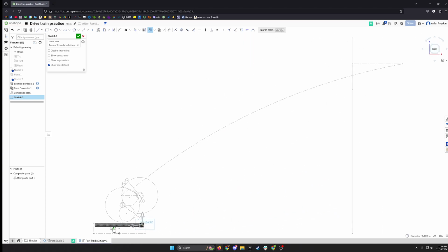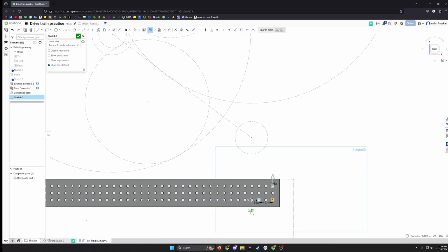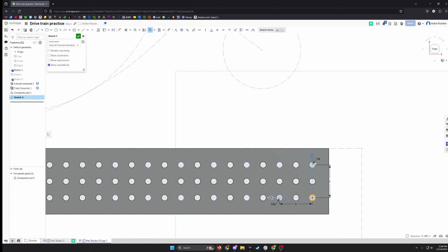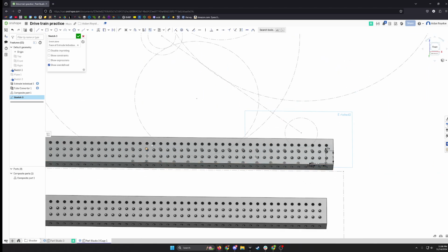And that's about where we want it, because this is the farthest back point of the indexing roller, and we want it to be a little bit farther behind that, so we have some extra support. So then we have all this bottom row done, and we can kill 2 birds with 1 stone by just coming up here to this 1x and just changing that to a 2. And this 1 inch is still correct because it'll be holes along this top row. So we can click the check mark, and just like that, we have all of our holes patterned for mounting.